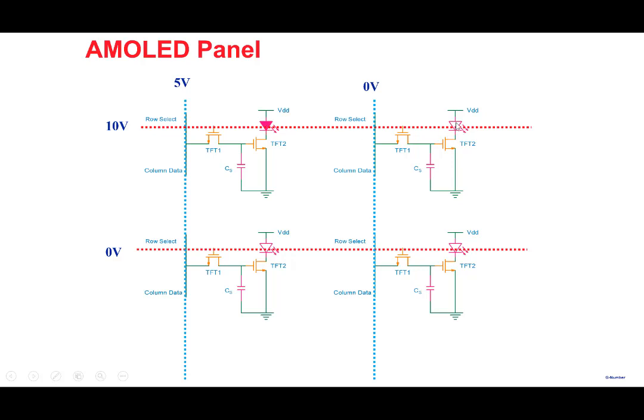In this case, we don't want this LED to be on. So what we do is we pass 0. When we pass 0 here, this switch turns on. And even if this LED was on earlier, and there was some charge on the capacitor, it will immediately discharge to 0 through this switch here. The capacitor will discharge and the LED will be 0.